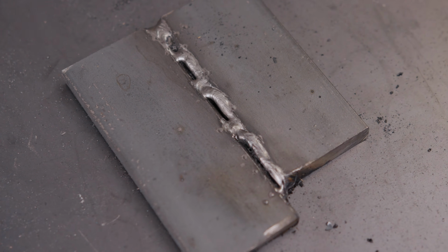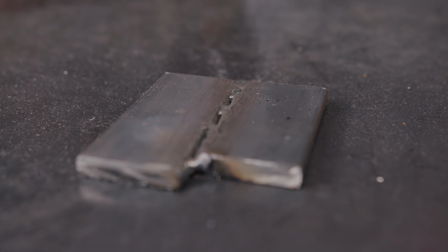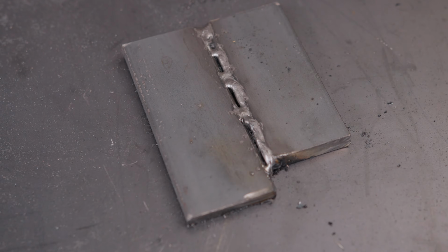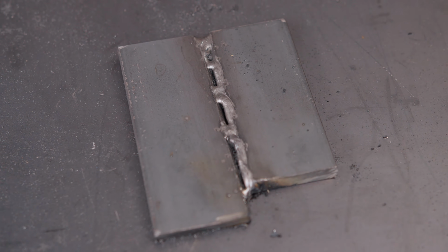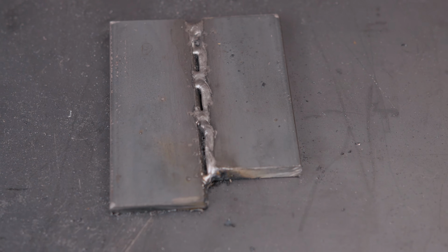A lack of fusion occurs when the weld metal doesn't fuse with the base metal properly. You can also have a lack of fusion between multi-pass welds. There are often gaps along the edge of the weld, and it's usually characterized by a high crown weld bead. You might not be able to see how the weld's fused on the actual weld, but if you can break it apart by placing it in the vise and cracking it apart, then it wasn't fully fused together properly. You can also check the fusion with an X-ray or other non-destructive methods.